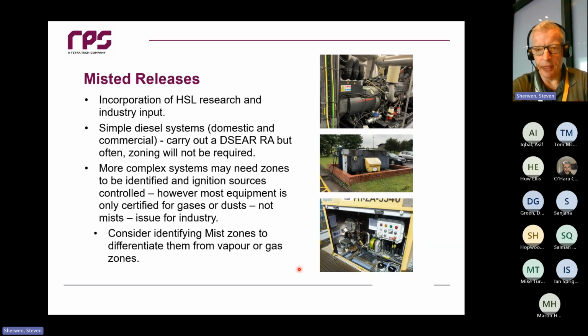And everyone's favorite topic, diesel. It always amazes me whenever I do these talks, and it was the same for the 4th edition when it came out. There's lots of changes, lots of technical innovation, lots of clever stuff, but all everyone wants to talk about is diesel and mists. In the gap between the 4th and 5th edition, as you probably know, the HSL and the HSE have done a lot of work on modelling misted releases of diesel, Jet A1 and other high flashpoint liquids.